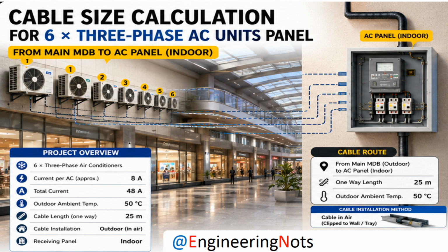At this point, we go to the cable ampacity table and look for a cable that can safely carry this current. But there is one very important point we cannot ignore. The cable is exposed to an outdoor ambient temperature of 50 degrees Celsius. So we cannot simply look at the standard ampacity table and choose a cable rated for 48 amps. We also have to apply the appropriate ambient temperature correction factor.